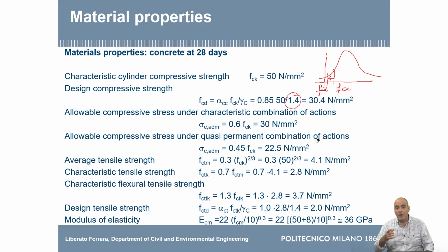In countries where you also have the snow load, also in northern India, it depends on the altitude. In some cases, if you have a lower altitude, the quasi-permanent fraction of the snow load can be 0. But if you go to altitudes above 2,000, 3,000 meters, then likely you might put a fraction of the snow load as a quasi-permanent load, because you can expect it to stay there for several months during the year. In some cases, you have even perennial snow, but on buildings, you have measures to take it out and so on. But you have to check for that.